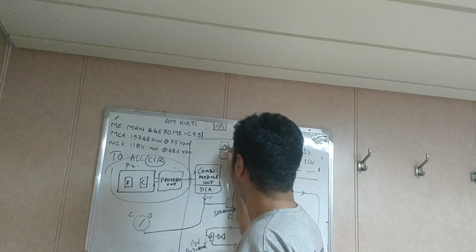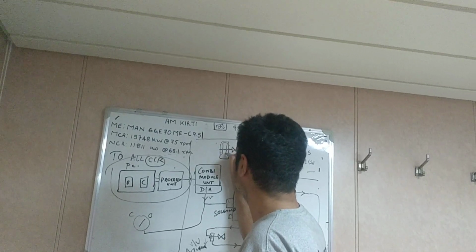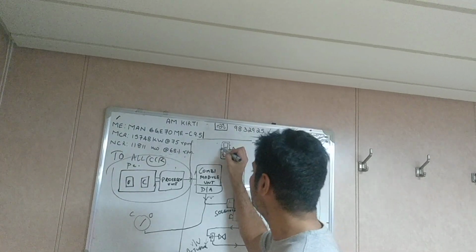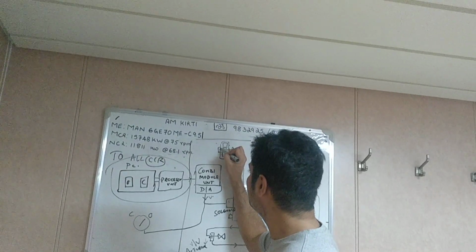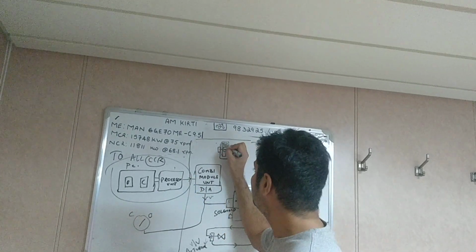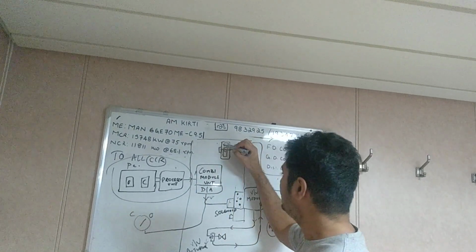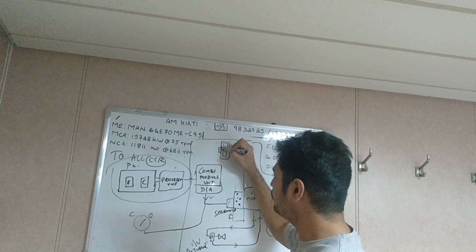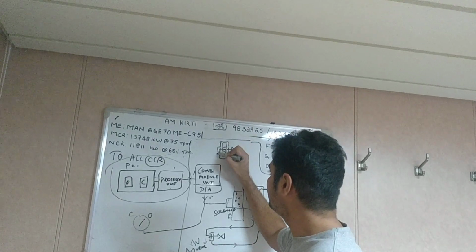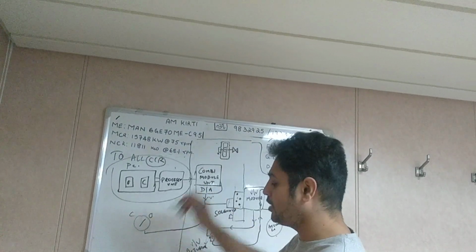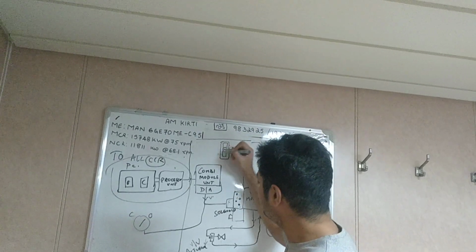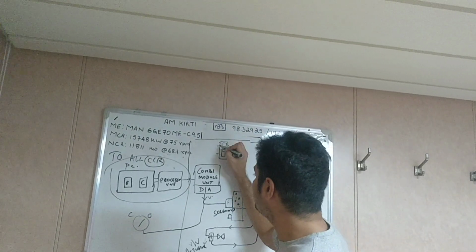This goes all the way, assuming this is a ram and actuator arrangement, where you will have a gearing and all. Here you will have a limit switch. If the movement is rotary, then there will be a position switch here, or if it is a sliding type, suppose assuming here there is one limit switch, here there is one limit switch.